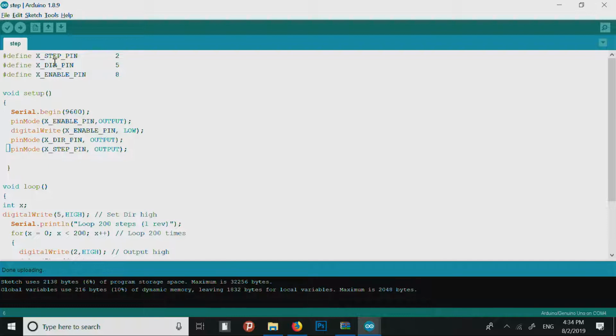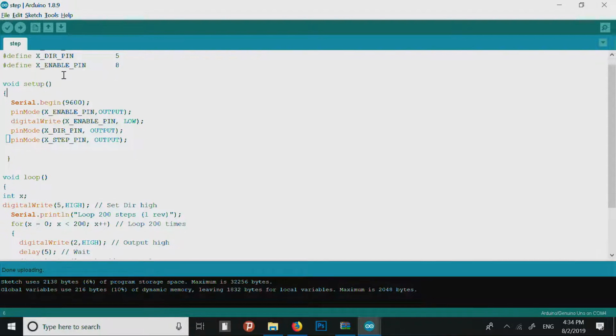There will be plenty of heat generated when we use these stepper motor drivers, and every one of them will have a heat sink also to transfer this heat into the air. So, you can see here the two inputs to the motor driver are the step pin and the direction pin. In the step pin you have to give the pulses, and in the direction pin you have to give either high or low to control the direction of the motor. And there is an enable pin. I do not think you have to care about that now. The enable pin is actually used for the CNC shield.